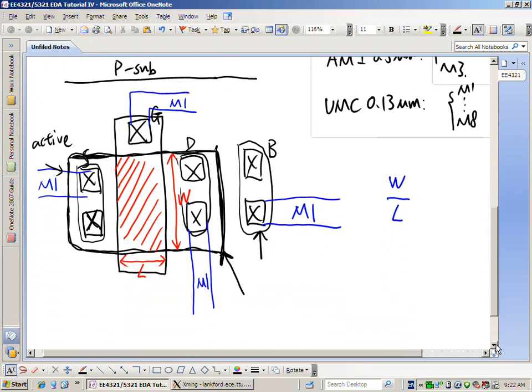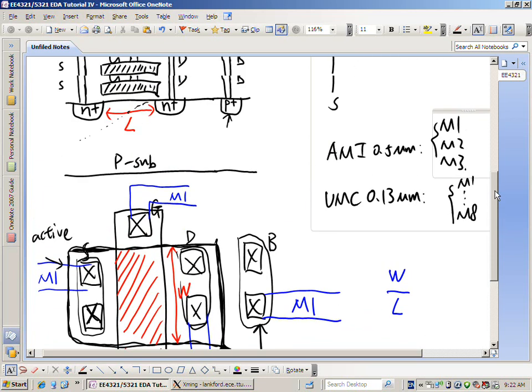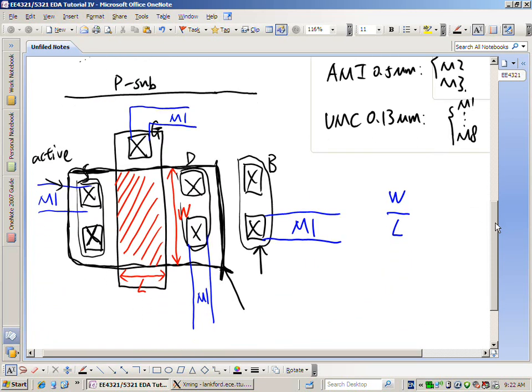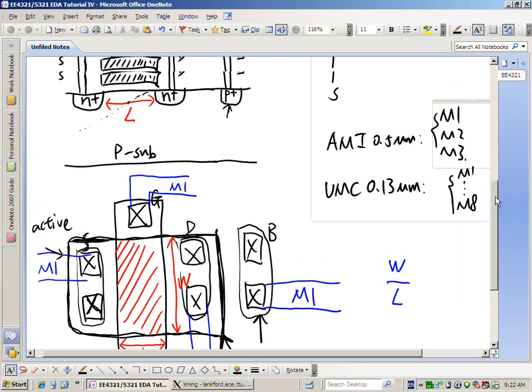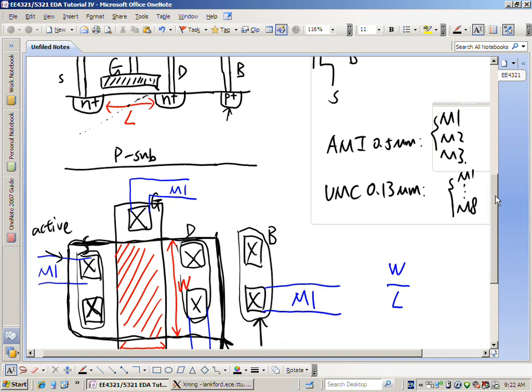Okay. This is actually decided by the foundry. When they define this kind of layout process, they made it simple, because either way, if you want to build a transistor, you must have two active regions, right? So you do this, and they have the gate overlapping your active region. So when you do doping, the N+ can't enter the area below the gate because it's blocked. Right. And this makes your life easier, because when you draw the layout, you only need to define one active region instead of two. That consumes less time for you, right?